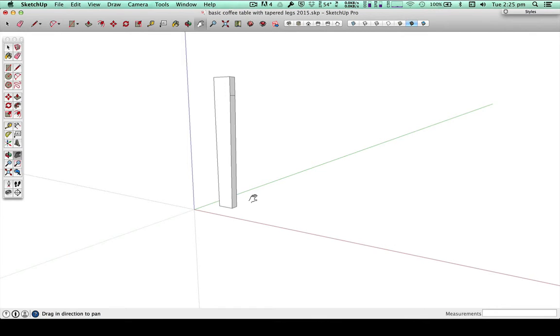Now with our legs, on the drawing, I know that our legs are 760mm from the inside here to the inside on the other leg. So all I'm going to do is copy it. Now the way to copy something in SketchUp is to hit the M button, that's the same as the Move tool. Then on a Windows, you actually press Control. On a Mac, it's Alt.